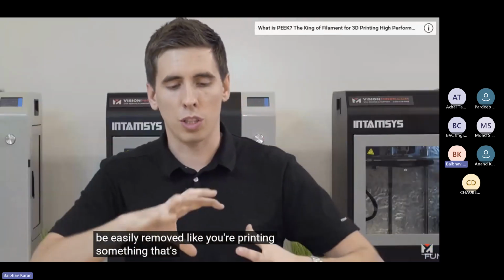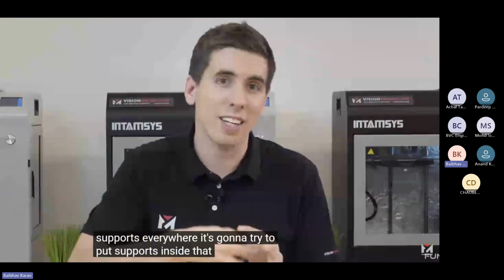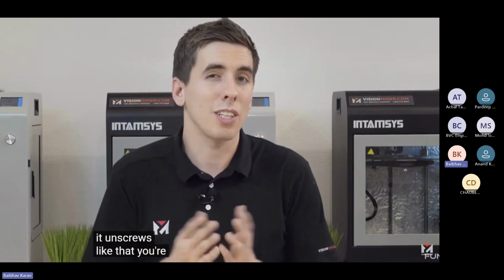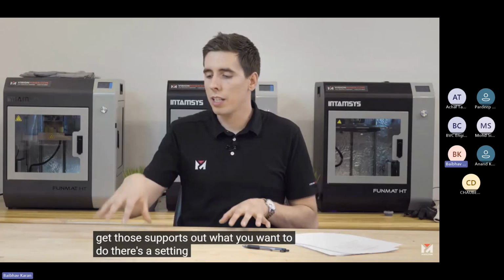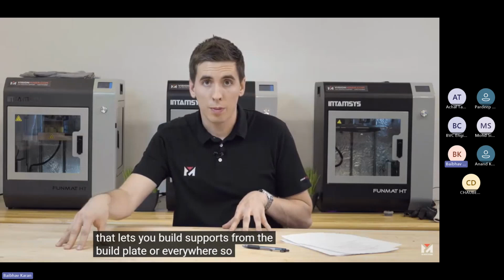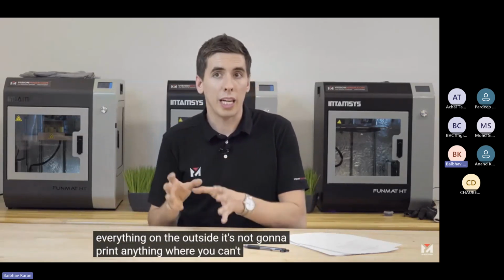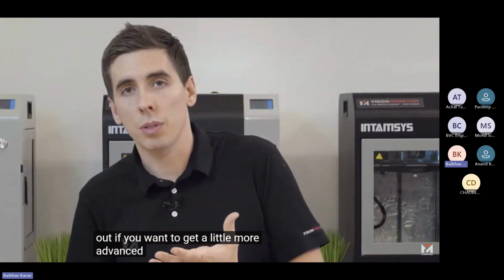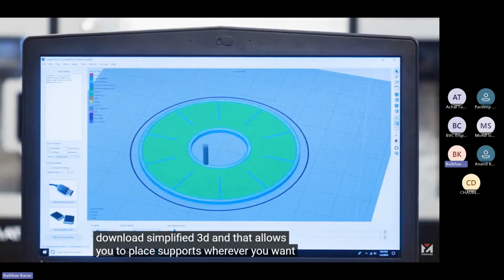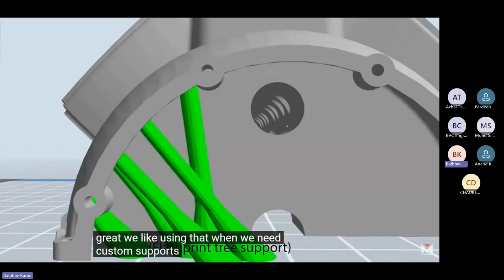Now, sometimes your slicer is going to place supports where they can't be easily removed. Like if you're printing something that's hollow, it's going to try to put supports inside that hollow object. And unless you have a big cavity or if it unscrews or something like that, you're not going to be able to get those supports out. There's a setting in most slicers that lets you build supports from the build plate or everywhere. From the build plate only is basically going to keep everything on the outside. It's not going to print anything where you can't get it out. If you want to get a little more advanced, you can download Simplify3D, and that allows you to place supports wherever you want. Fully customize it, works really great. We like using that when we need custom supports.